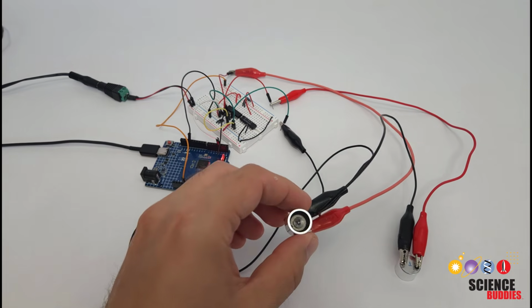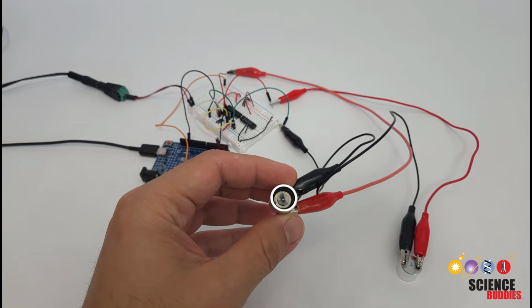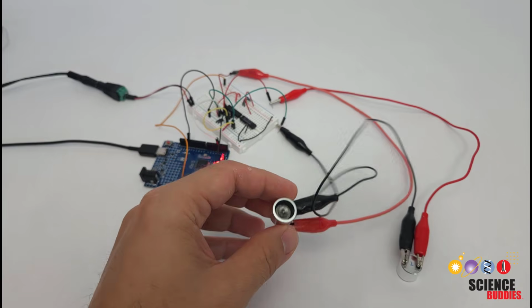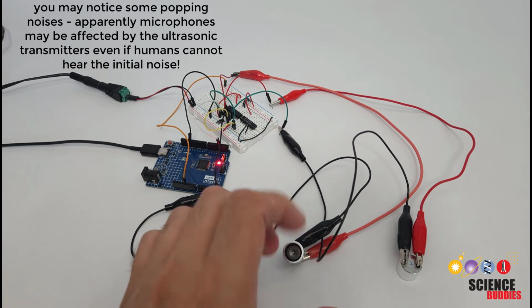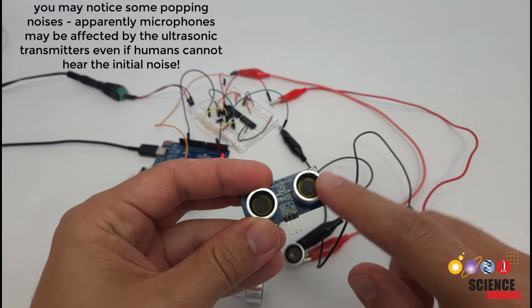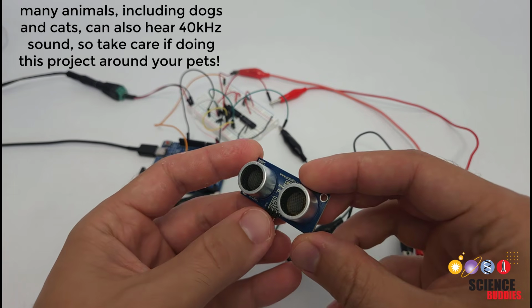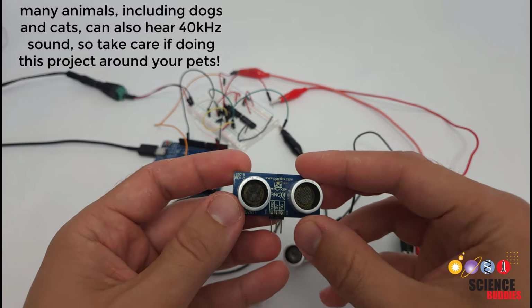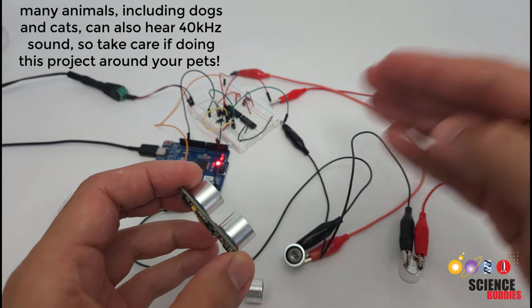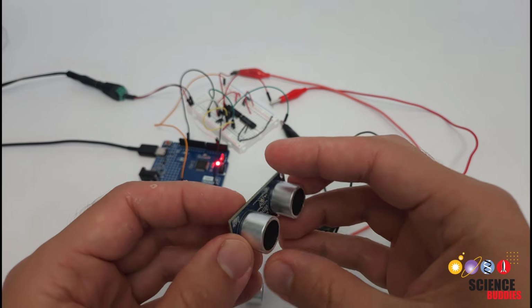Now, the heart of this project is these little ultrasonic transmitters, which you can think of kind of like a speaker that just generates noise that's in the ultrasonic range so humans cannot hear it. And you have probably seen these in pairs, a transmitter and a receiver that can detect or measure ultrasonic sound if you've ever used an ultrasonic distance sensor with an Arduino project. So these work kind of like a bat doing echolocation. They send out a burst of sound and then measure how long it takes to reflect back to the sensors.